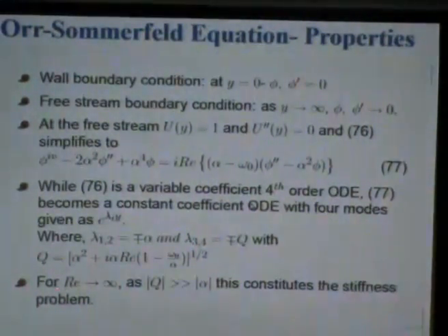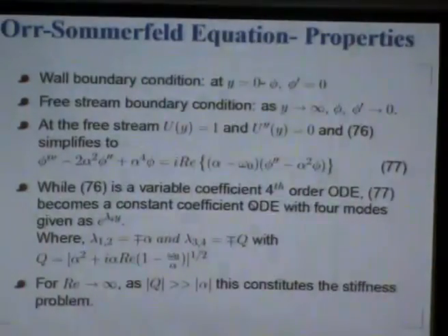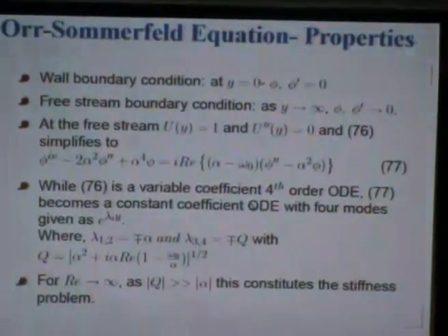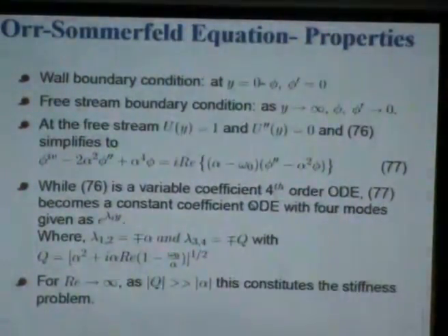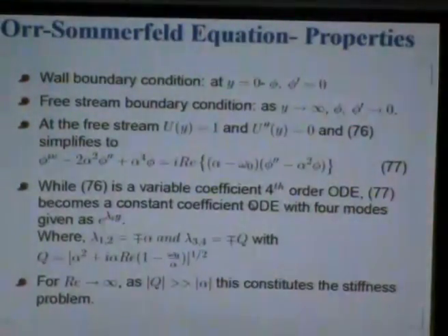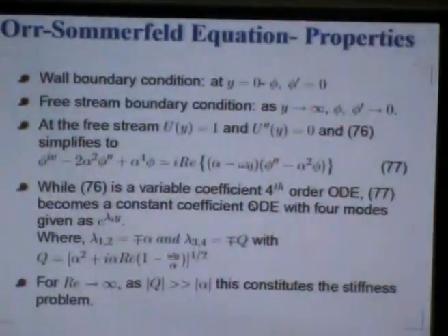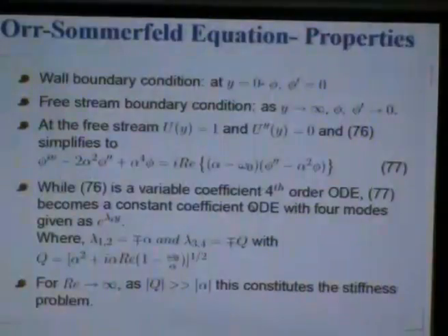That is one thing. The other thing is, most of these problems of instability arise when this parameter here, the Reynolds number, takes large values. You know, for flows at low Reynolds number, you do not see instability. Instability is characterized by a certain range of parameters, and in this case it so happens Re has to be large. Well, I have just shown you a sort of estimate.